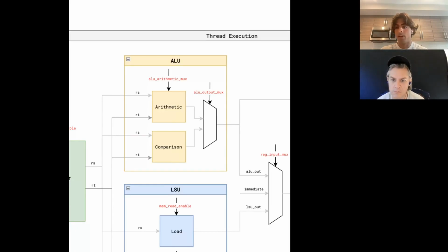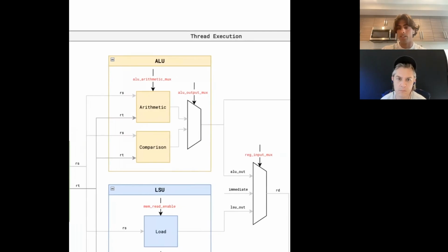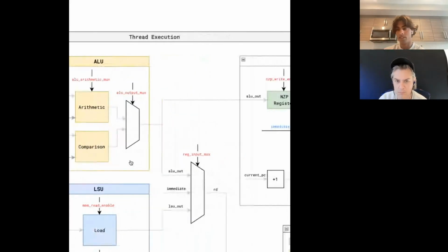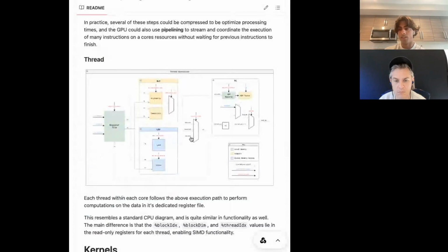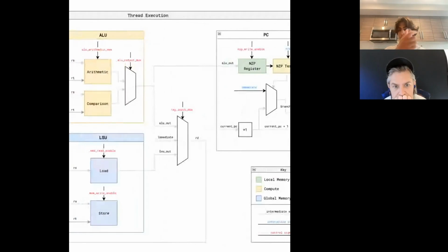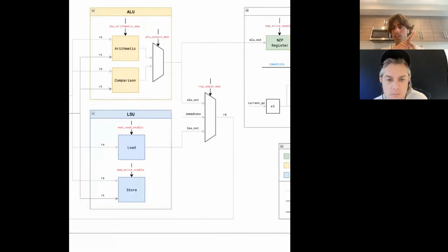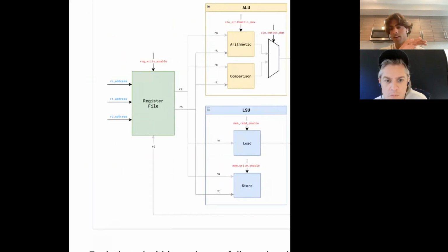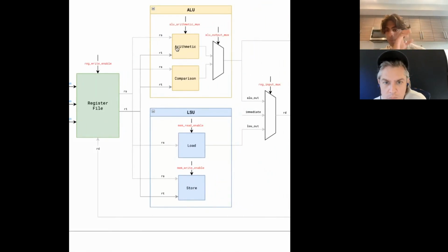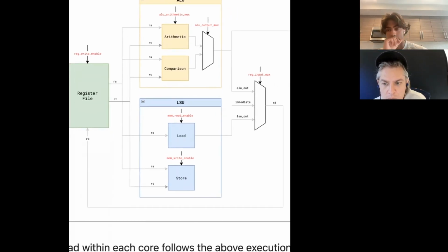And then that value, you can see in the rest of the design, most importantly, is going into the register input multiplexer. And so just to finish this part of the flow, the register input multiplexer is going to be 0 this time. It's going to say, hey, we got some value from the ALU, and we actually want to use the ALU value this time and store it back in the register. So you see, okay, we're choosing the ALU output, and then that's going into the destination register, which is what RD is. And we're going to store that back into the register file in the register specified by the instruction. And so now you see, okay, that's actually a full loop, for example, with the add instruction. It's basically completing the addition, choosing to output that addition from the ALU, and then choosing to store that output back in the register file. And that's really how you get the addition value.